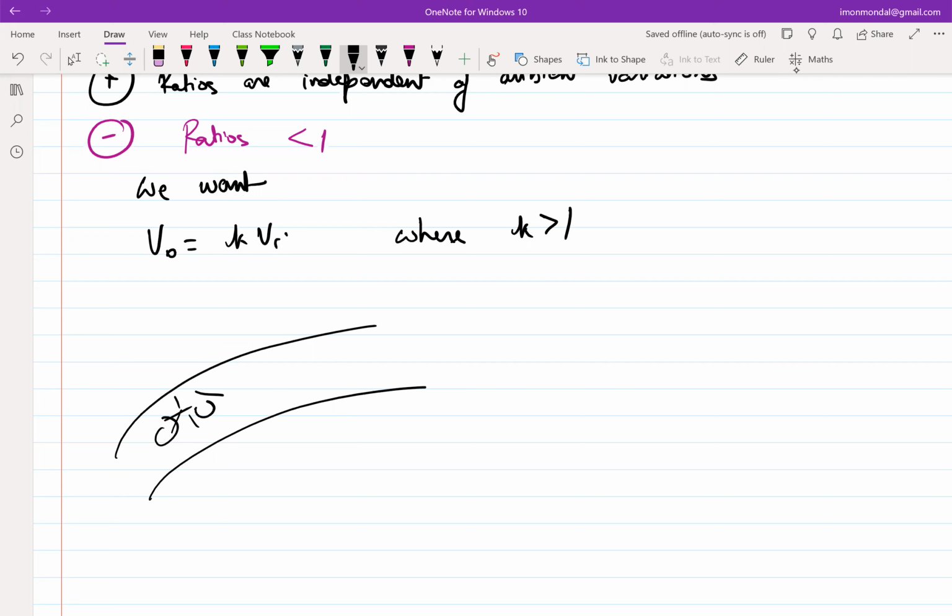Okay. So the intuition with which you ride a bike is you see where you need to go, what is your desired path, and you apply a torque and see where is your actual path, right? When you turn, the bike goes in a certain direction, and that is your actual path. And if the desired and actual are different, you take a corrective action, right? You either apply more torque or you apply less torque, depending upon what is the characteristics of the handle, right? So essentially, you ride your bike with the concept of minimizing error through negative feedback.